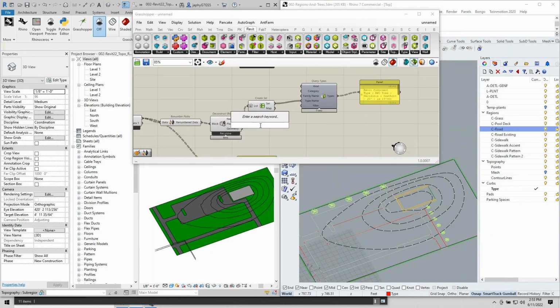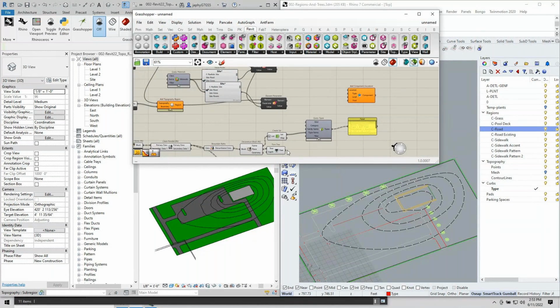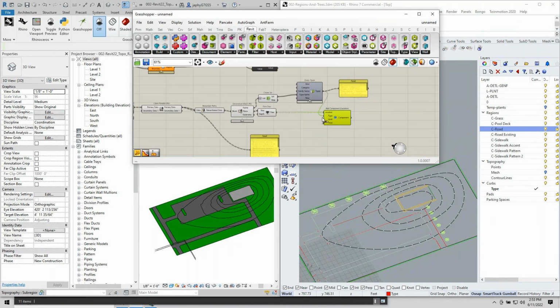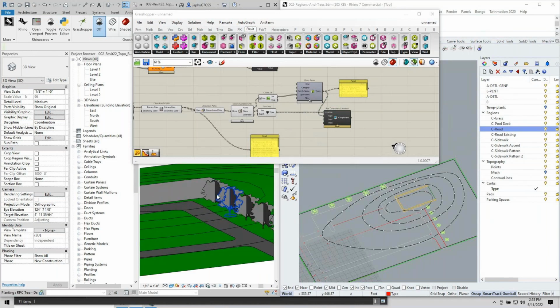So we're going to need to trim the tree, which is a really common Grasshopper practice. Now we have 2 branches, 0 and 1, that match our types, 0 and 1, and we can add in our location. So we'll go ahead and add this location, add by type. All right, so you're going to see that our trees are buried.